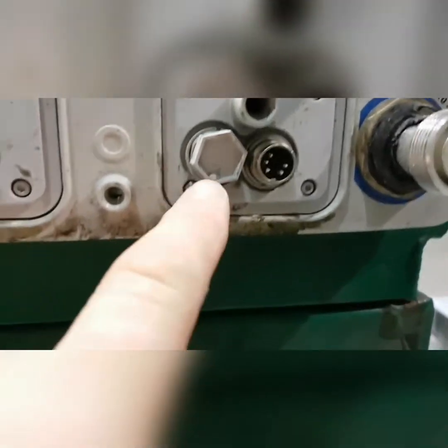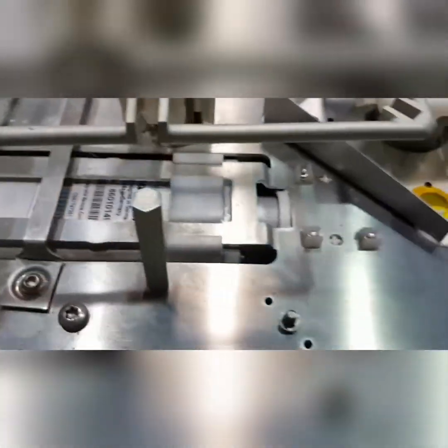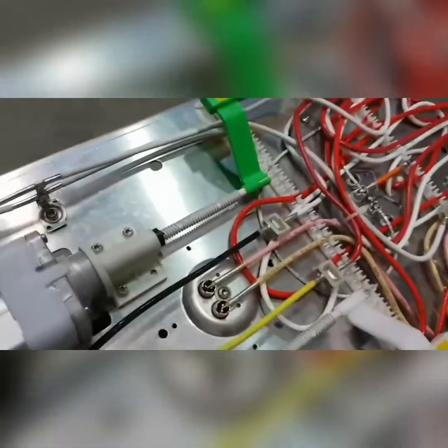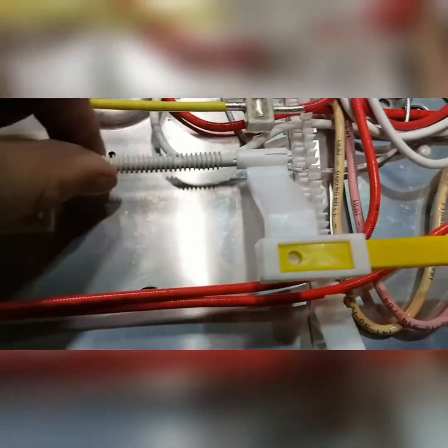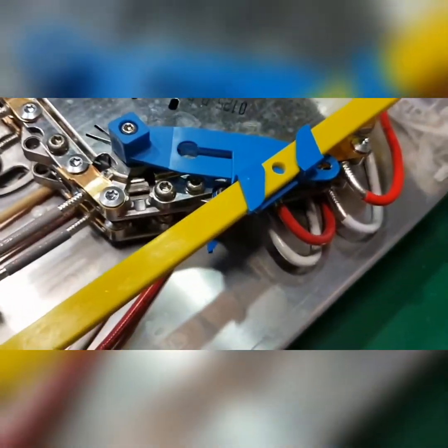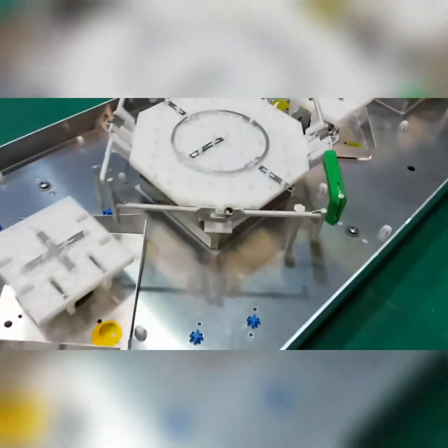It's because these here are electrically controlled motors that tilt the inside of the antenna. There you can see the motor itself, and as it actuates, in behind here, it actually moves this bar here up and down, adjusting inside of here how the electrical signals are sent out the front of the antenna here.